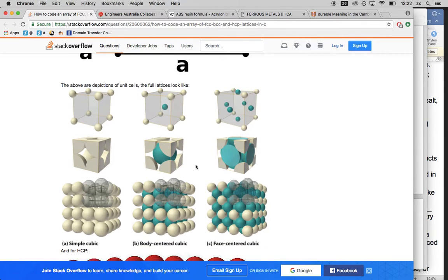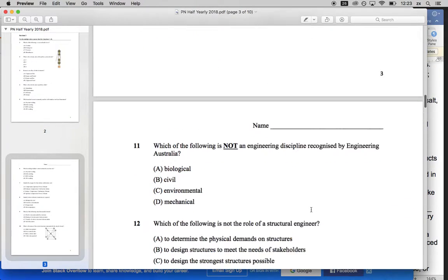So we have common crystal structures that we talk about. There's a few common crystal structures, but we really like to try and keep it fairly simple. We talk about BCC, body-centered cubic, and FCC, face-centered cubic, and we can see the difference in the arrangements of the atoms, or the ions in the case of metals, how they arrange themselves. There are others that we need to know about. HCP is hexagonal close packed, and we often talk about BCT, body-centered tetragonal, but we haven't talked about them in great detail, and we'll be talking about them more later.